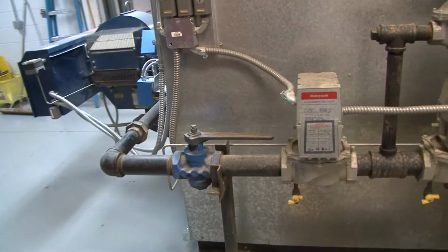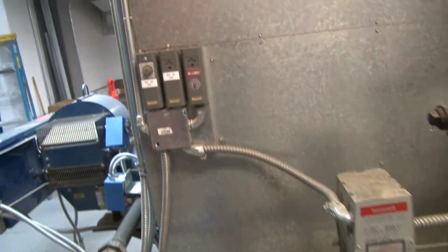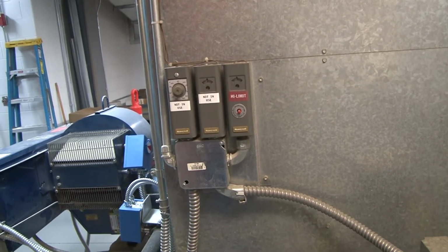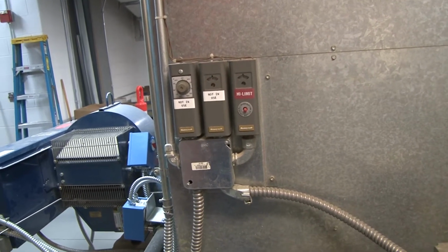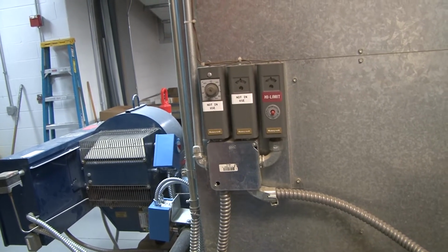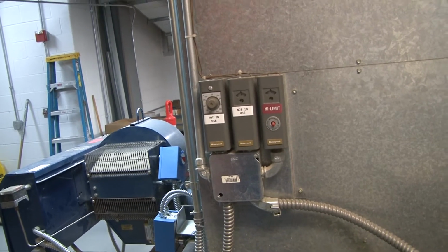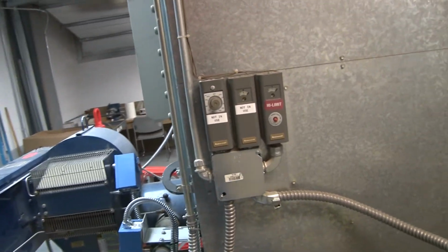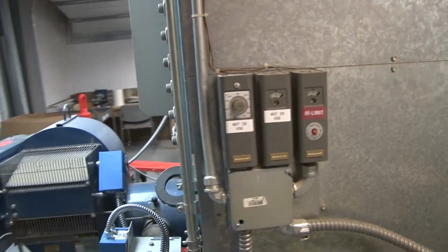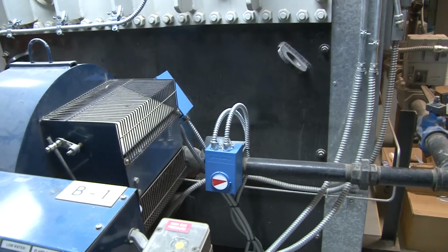We have our isolator valves here to stop the flow of natural gas, and we also have our high limit, our operator, and our differential sensor that was used to anticipate the operation or the temperature and operate the boiler. But note that these are not in use anymore, and the reason why is because, just like in previous videos,